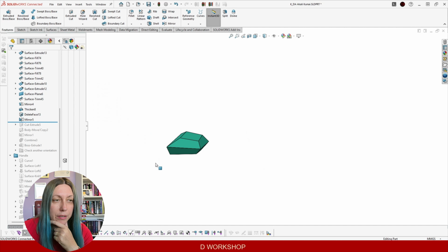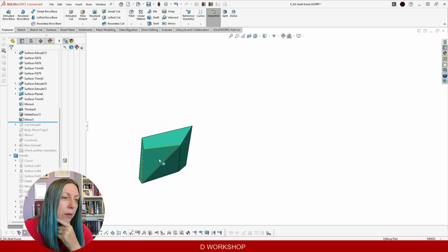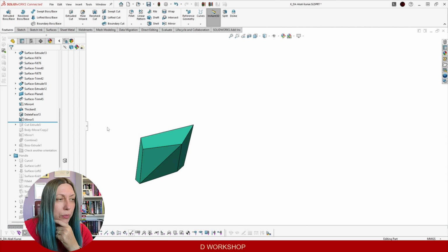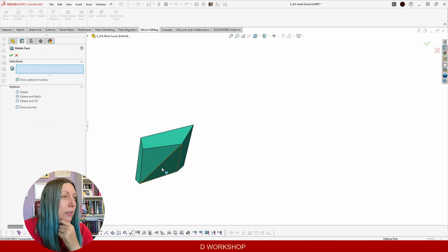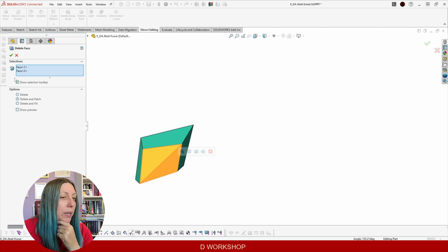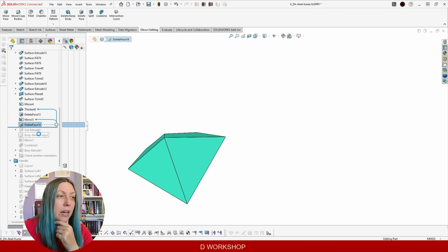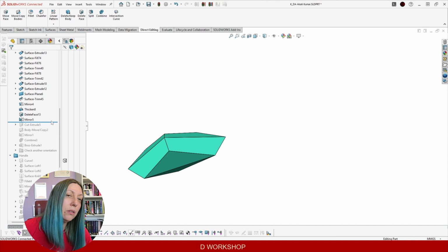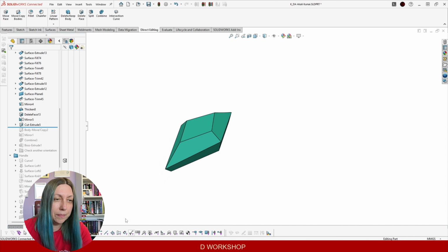I mirror it and receive some kind of weird shape because of here. I won't be able to print it normally. Usually I like direct editing, and when I make the lid face here, I have a problem because it makes it like this. I don't want it like this, I want it straight on the bottom. That's why I use just extrude cut.